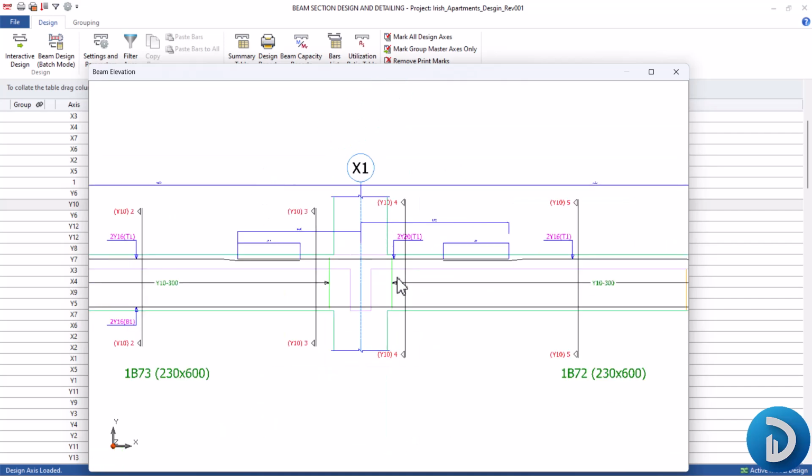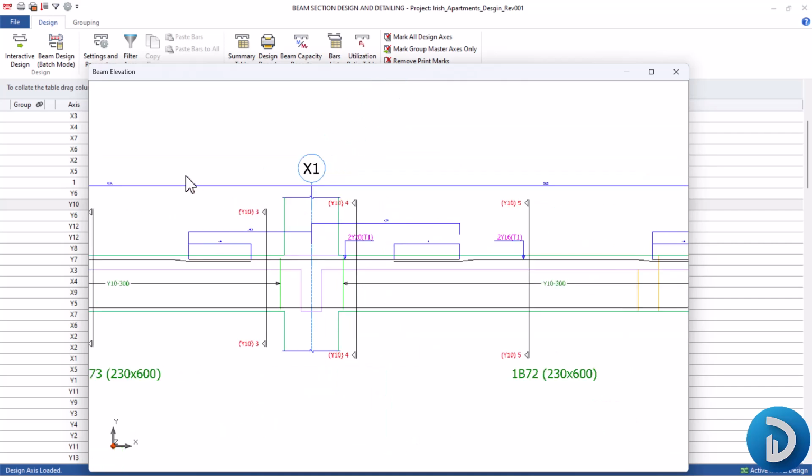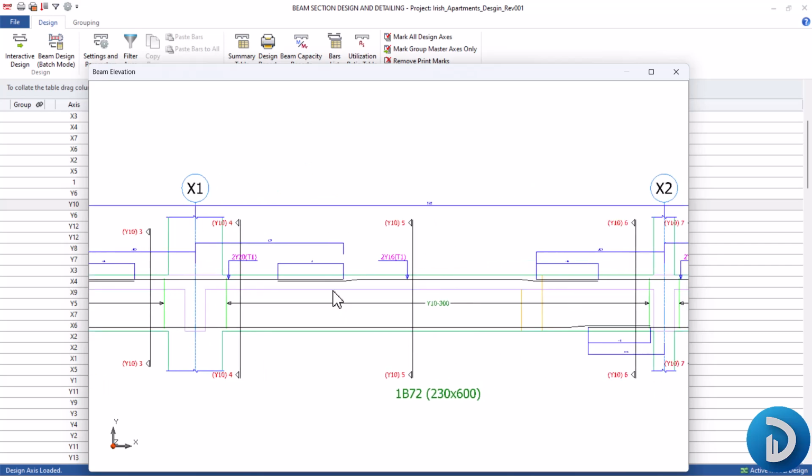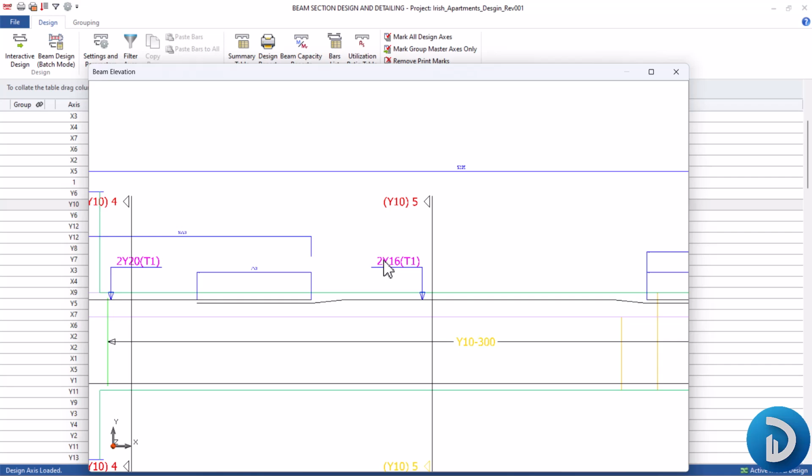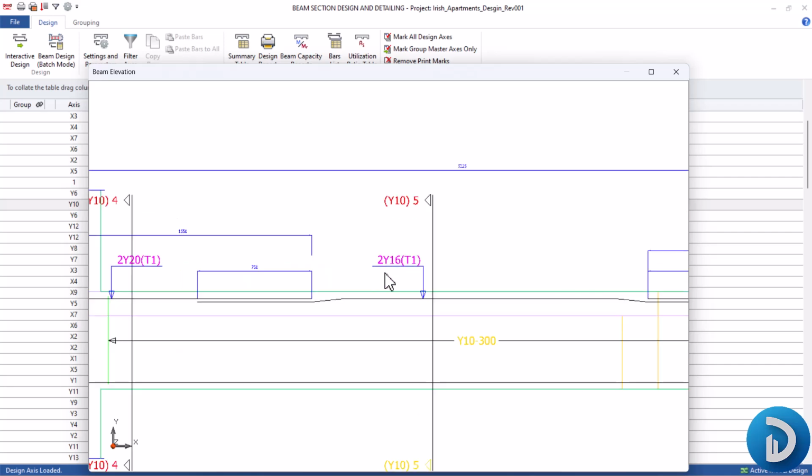After this support area, moving on to the next span zone, which is experiencing compressive forces, you will see that our reinforcement here has been modified to two numbers of Y16, which is our minimum hanger bar that was selected earlier.